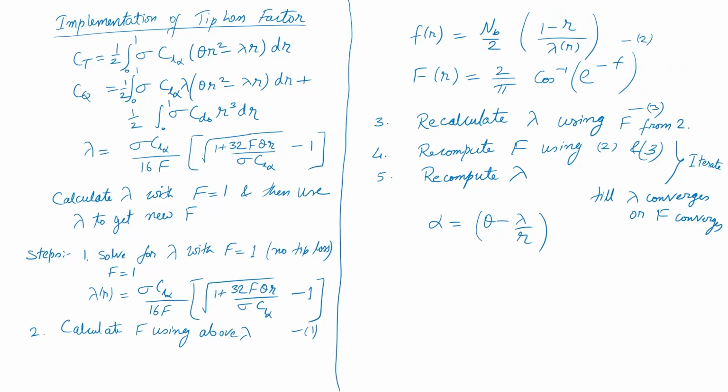I hope this is clear, how to implement this part. Any questions on this? The torque that you have taken here is a sum of quotient on thrust. What is the second element in that, sir? No, these are the two parts. My torque expression from earlier, I just copied the same thing. So it has an induced power part and a profile power part. This is profile and this is induced. This is lift into lambda, so lambda dCT is my induced power, and the integral of your drag is your profile power. It is the same expression as before, it is nothing new.